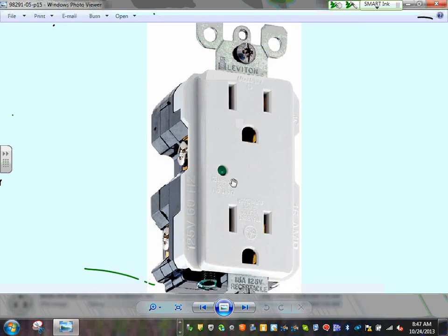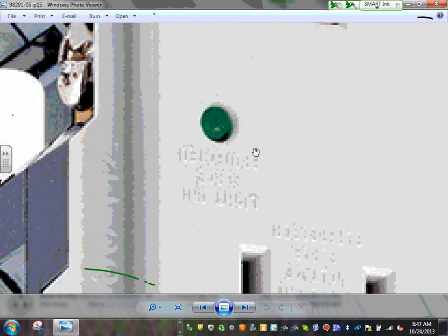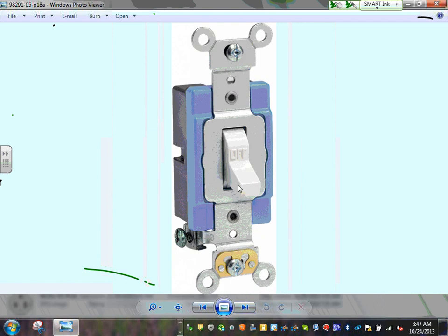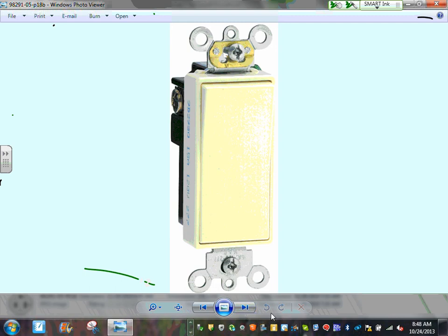Lots of decorative receptacles, guys. It looks like this is a surge protective one or what's not. So you can have surge protective devices and what's not. Here are what amount to spec type switches, guys. Does that look like the one that you use in your house? Do you see the skinny ones that we use for residential? Can you use them in commercial? Yes. Should you use them in commercial? No. They're more robust, the ones that we use, the switches, different decorative light.